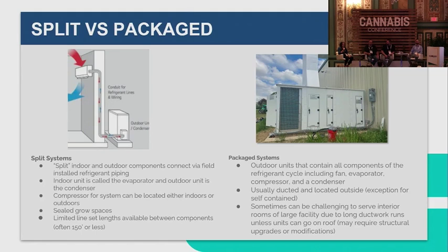So yeah, there's pros and cons to both approaches, but safe to say, split means it's a split package unit, essentially. The name is what is implied, right? Split versus package, yep. I think the big thing to consider also is you've got refrigerant piping when you have a split system. It could be a mini split, fairly common, fairly easy. It could be a complex split system with hot gas reheat, hot gas bypass.